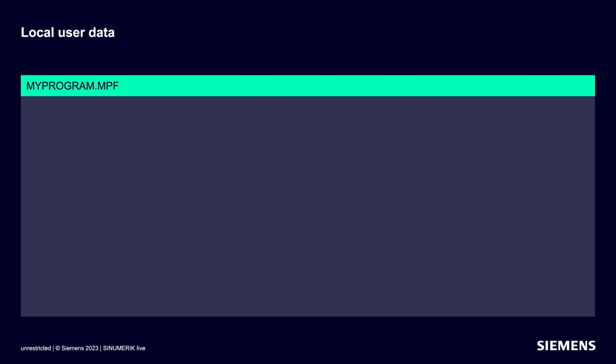Here we can see a CNC program in the CNC editor that's still empty. While I create this small CNC program, I'd like to explain the syntax. Let's enter the first instruction, the language command def. This is how we define our local user variables. By the way, CNC blocks with the def instruction must always be placed at the very top of the program.